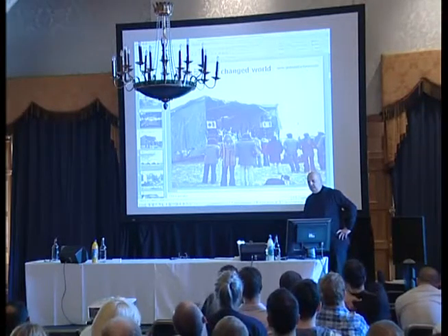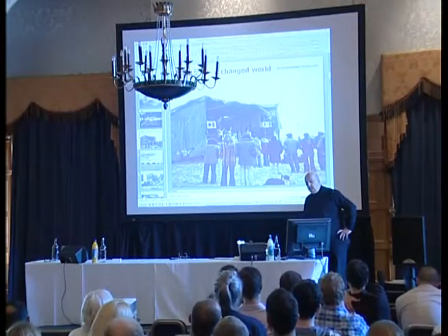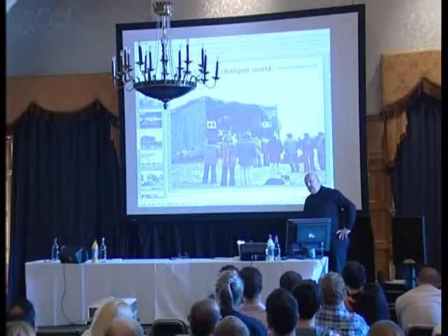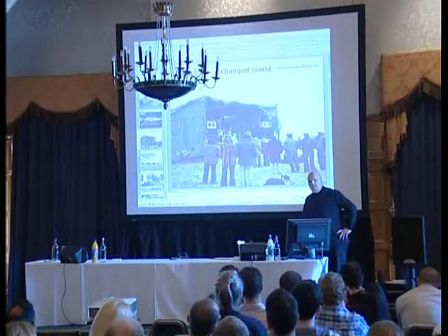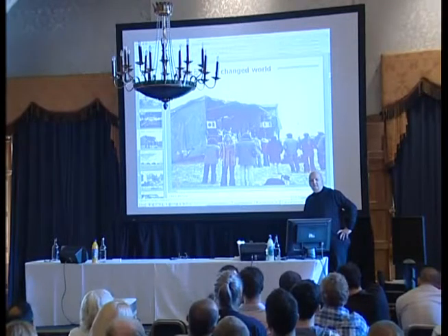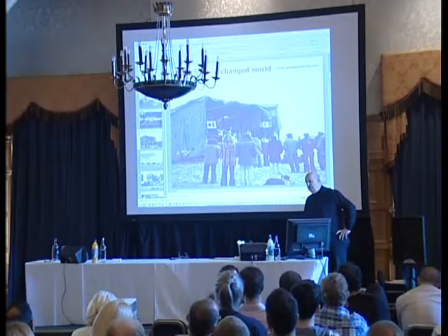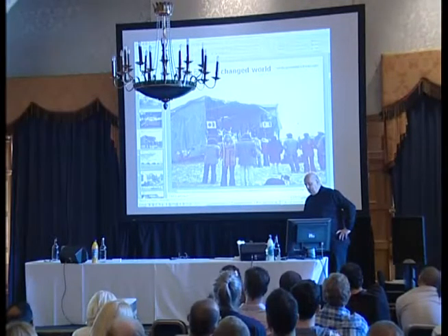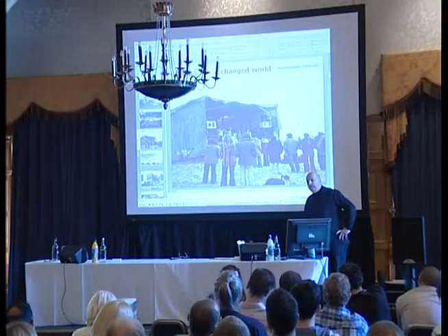If you look at some of the video, you will see that one of the 6 king poles on the big top stayed up. In the time it stayed up, 1,000 people got out of that tent. I mean, some were killed when the first poles went down. But the fact remains that one king pole was held up with a 16mm guy and by one anchor. How it stayed up, we don't know. And it's quite clear looking at the video that there's not much there holding it up. And the question that I ask is, shouldn't we be putting extra anchors on to allow for that kind of eventuality?